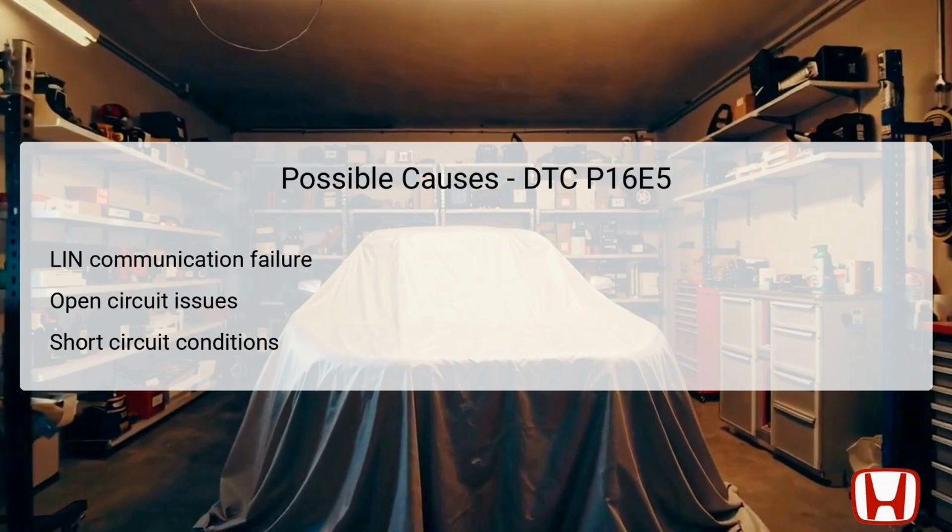In contrast, short circuit conditions might occur if a wire contacts the ground or another live circuit, confusing the signals sent to and from the PCM. Identifying these conditions through systematic testing is essential to addressing the underlying problem causing the DTC.